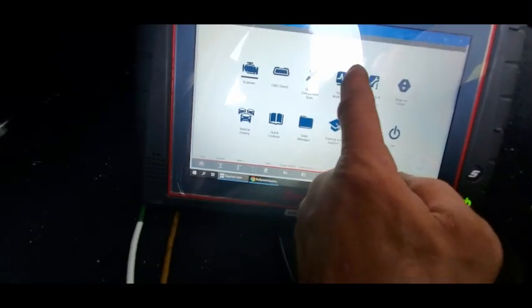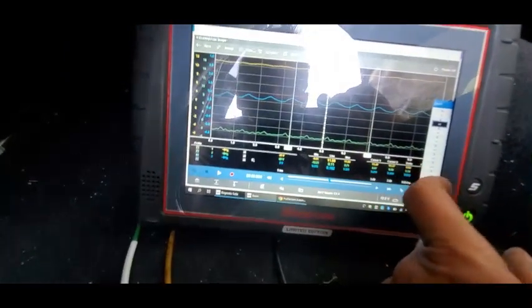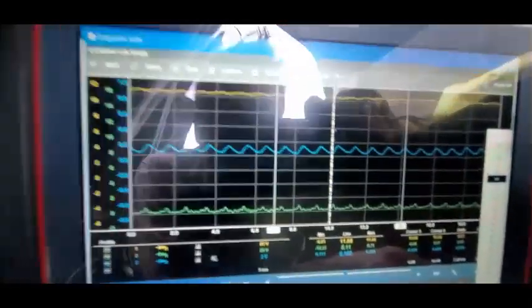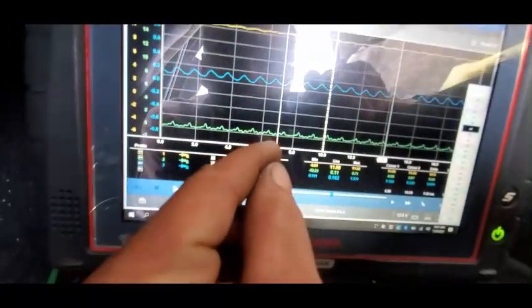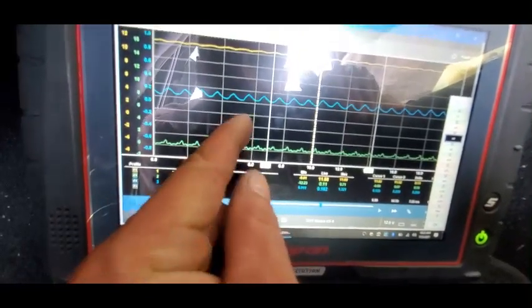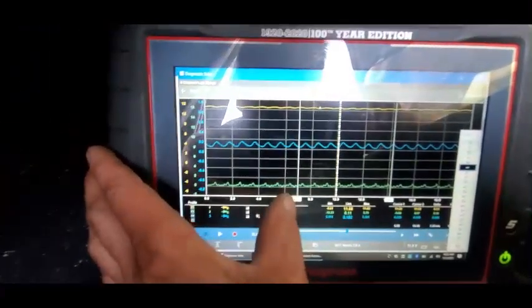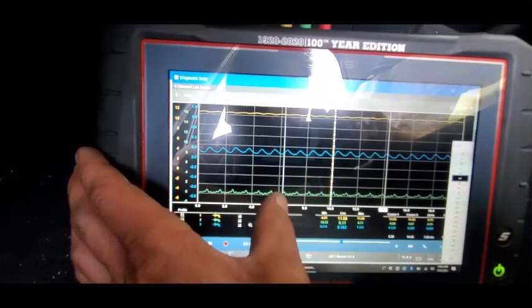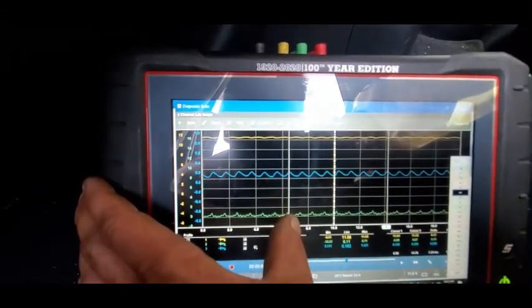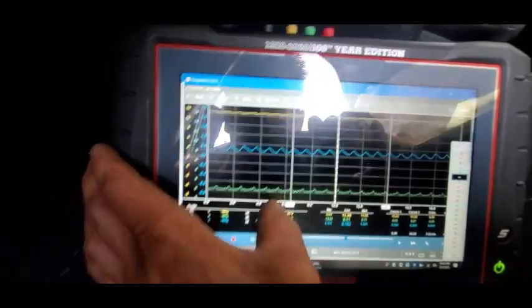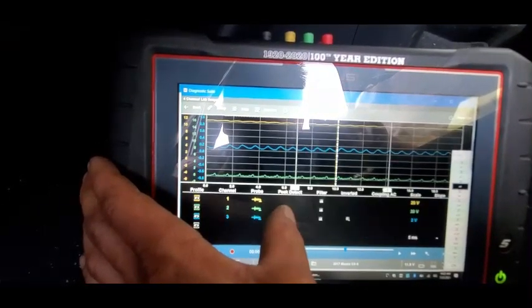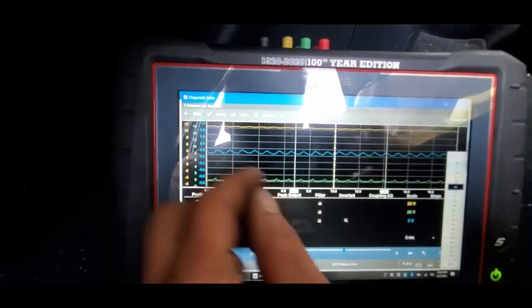So, let's see here. Let's come out a little bit. That is our ramp. So, what are we getting for a speed there? That's 100%. That's got to be 100% duty command. So to see the pulse width modulation, we're gonna have to put the pump in and get this thing running. I know it needs a pump.